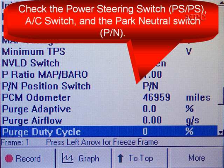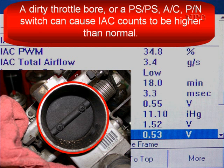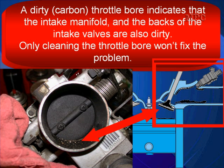Check the power steering pressure switch, the AC switch, and the park neutral switch to see if they're sending a command to the PCM to raise engine idle. Also check the throttle bore for restrictions. You can see we have a dirty throttle bore here. Now a dirty throttle bore, or the power steering pressure switch, AC switch, or the park neutral switch, can cause higher than normal IAC counts.